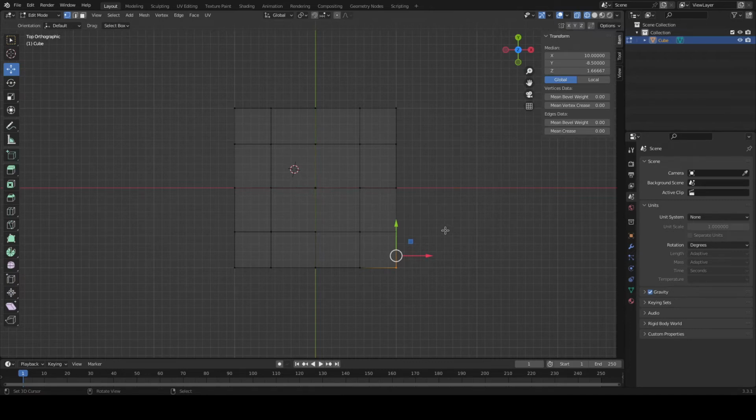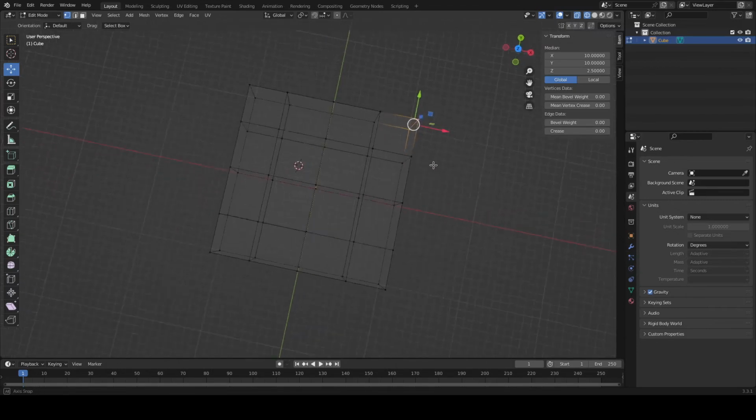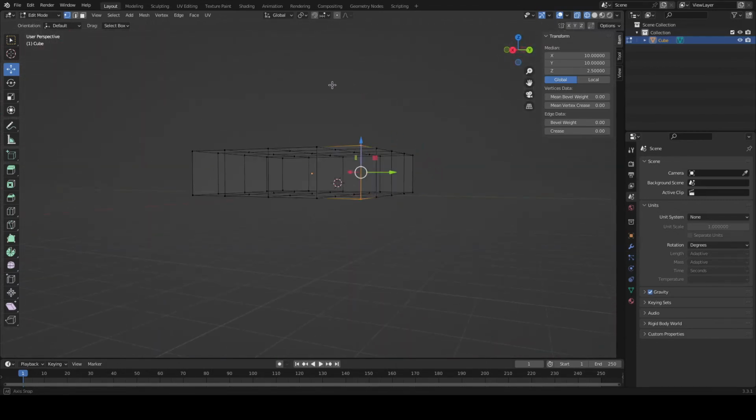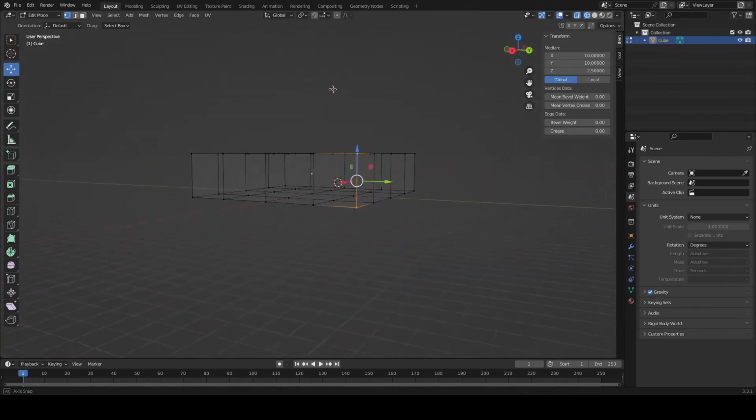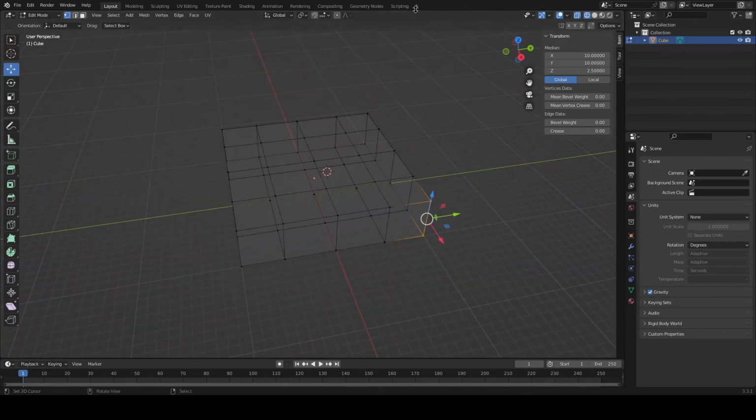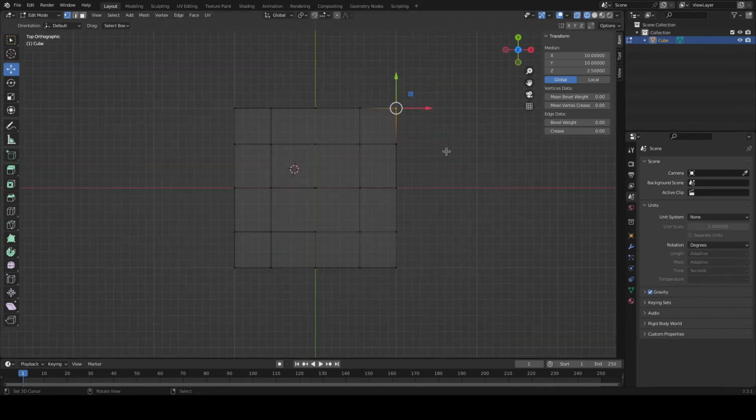And the next thing that we're going to do is I'm going to prove to you that when we box select, we're grabbing more than one vertex at a time. So here we are in the top view. I box selected two vertices, and you can see that they're both selected. So I'm going to press 7, and that's going to get me back to where we were.